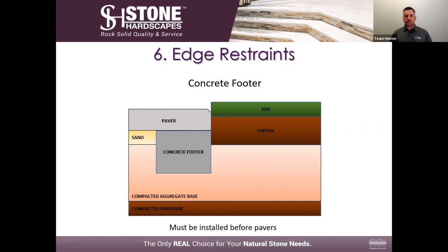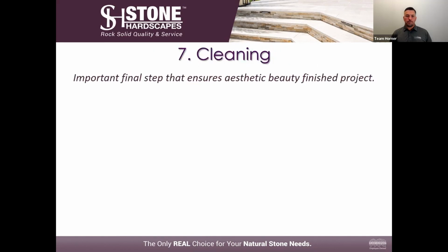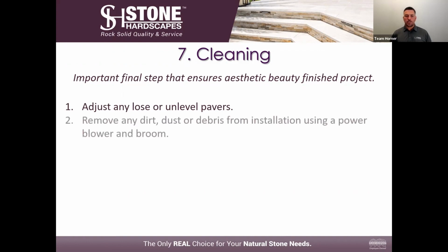Now that we've got the deck done, we've got the footers in, we've got the restraint in, everything's done, the deck is finished. Now comes the cleaning. This is an incredibly important aspect to ensure the aesthetic beauty of the finished product. This is the time now to run along and adjust any of the loose or unlevel pavers to get in there and really clean up the installation.